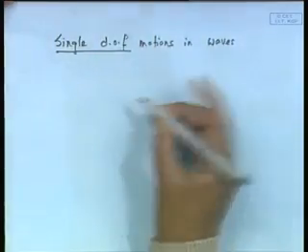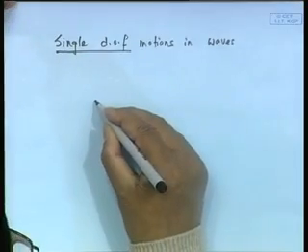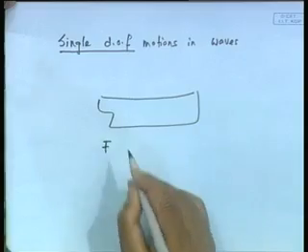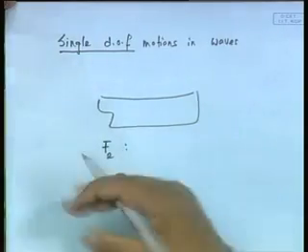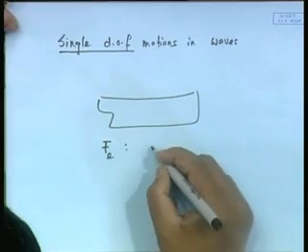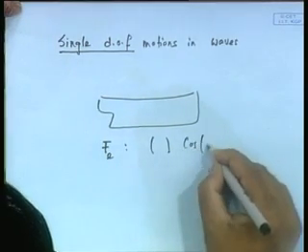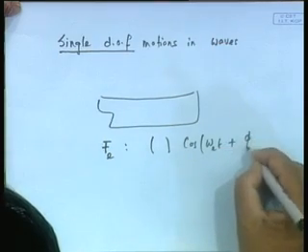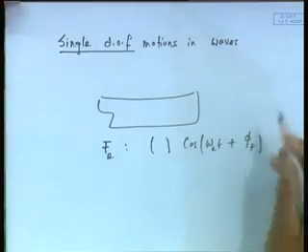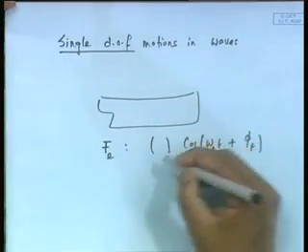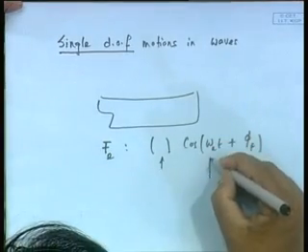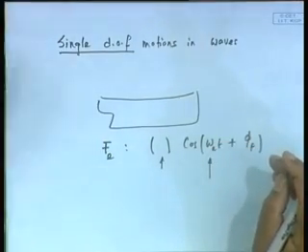Now, you see in the last lecture we saw that if I have a ship, the excitation F, if I call it the wave induced force, would have a periodicity of omega e, that is it will be something into cos omega e t plus maybe some phase gap. In general it will look like that, the excitation. We do not know what the excitation is, but of course we know it will have a periodicity of omega e, because it is coming at omega e.